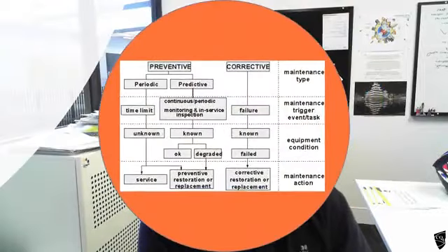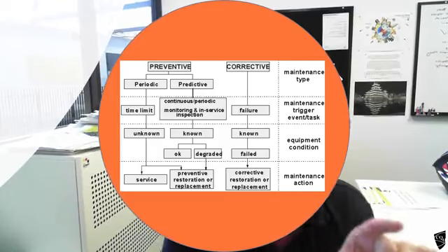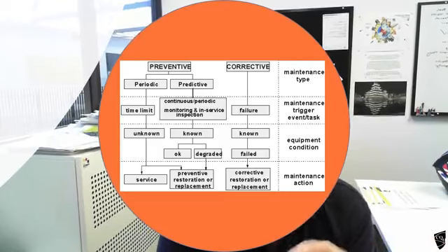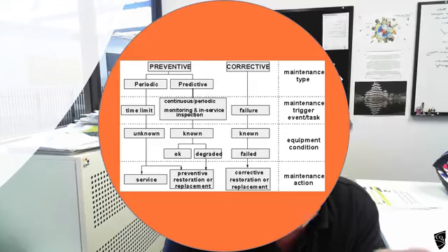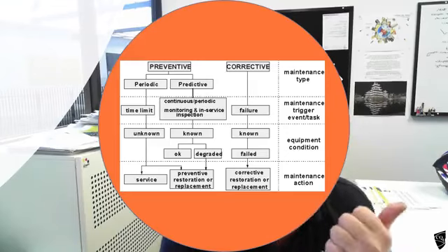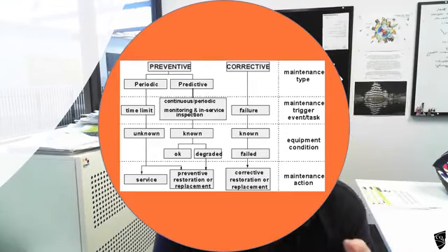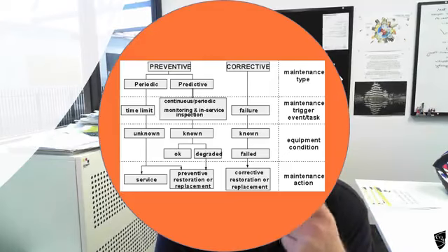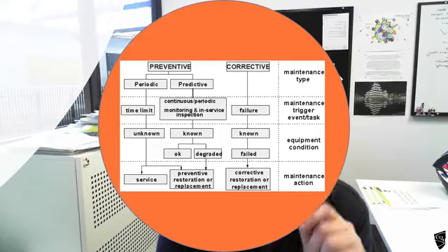And just to recap on what we looked at before, the difference between the preventative and the corrective maintenance. Preventative, periodic, predictive, we know it's coming, it's not a surprise. It can be based on a time limit, or it could be regular, like a lift would be a regular, and gas boilers and chiller units for air conditioning, all regular. Periodic ones can be unknown, but predictive, you know what they are. But the corrective ones generally only come up when something fails.